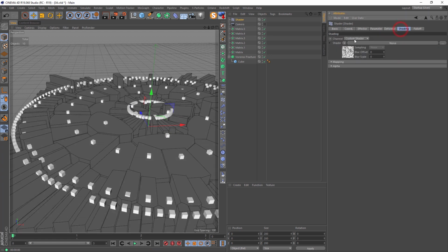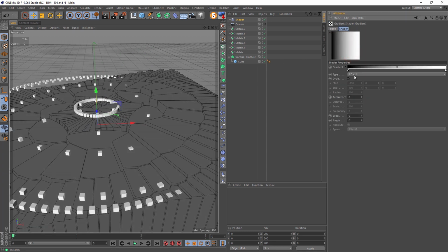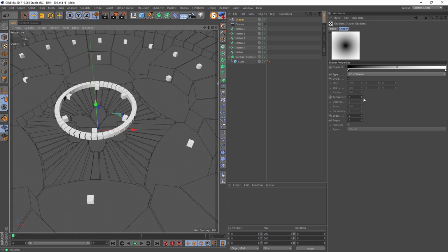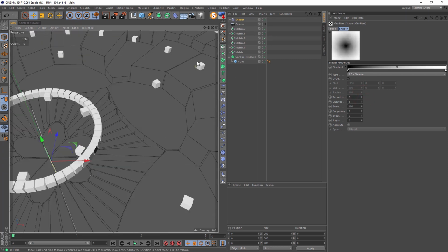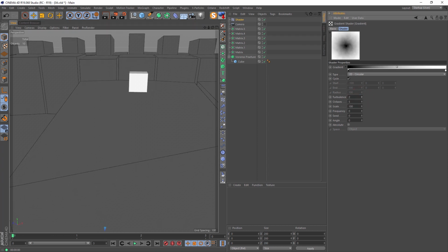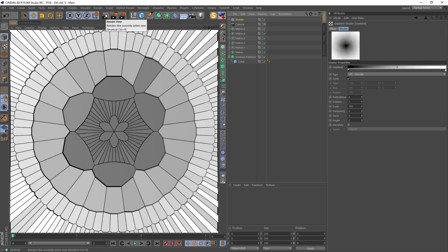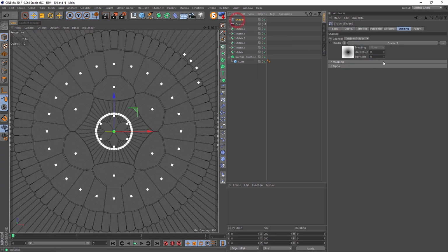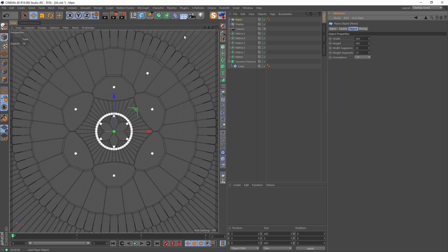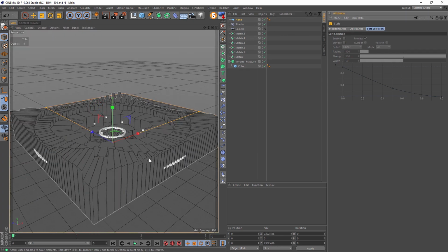As I said, we can use not only noise, but we can use gradient, let's start from circular. We can add some turbulence for some randomization, you'll see. A little randomization. And when we render, we'll see that flat look. That's not good, that's not interesting, we already did this. I upscale a bit, create a plane, a very wide plane, so it covers all these holes between elements,